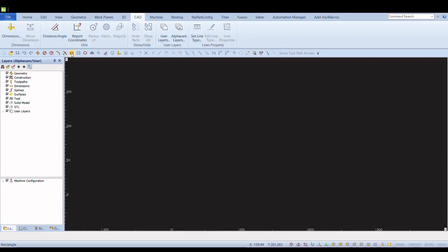To start, we're going to select the rectangle command. From there, look at the bottom of your screen. This is where you're going to always enter your information needed. The rectangle is going to be 13 feet wide by 8 foot tall. So for the x-axis, we're going to give it a starting point at 0, hit enter to move to the y, and enter again for 0 there.